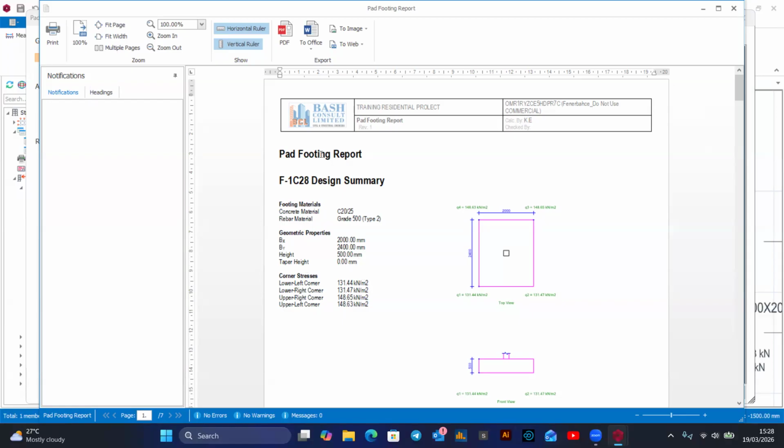Now, that contact area, you will not have control over it. It is being dictated by your allowable bearing capacity. You get it? If you put in the allowable bearing capacity and the software finds from its computations that the average pressures on the different vertices of the footing exceed the allowable soil bearing capacity, then definitely it will demand you to increase the contact area. You increase it until you find that the design is successful to your satisfaction.